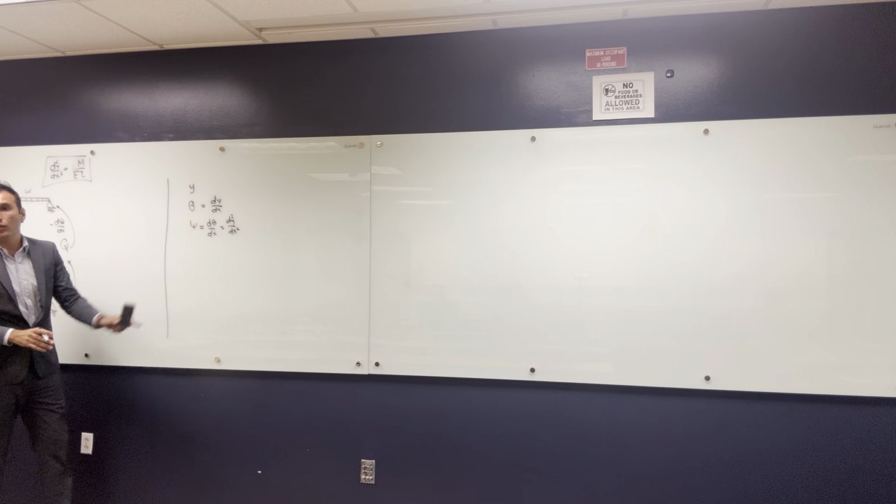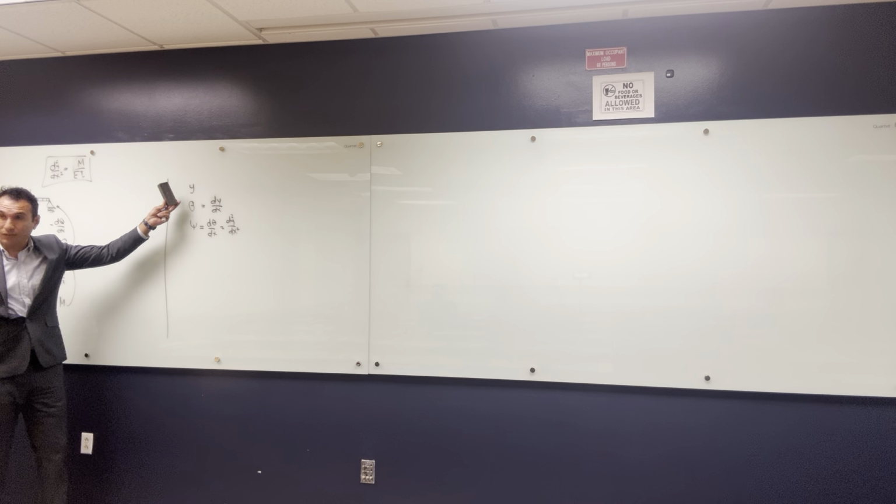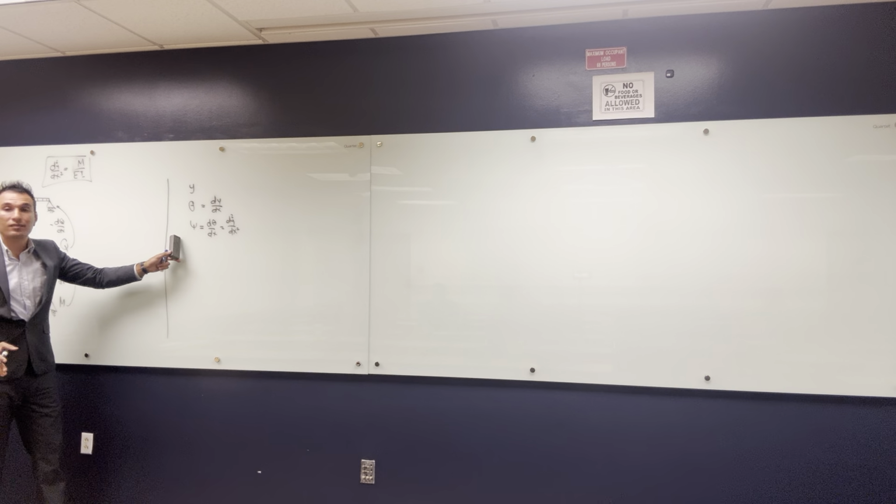So when we say deformation in a beam, we mean these three quantities, y, theta, and psi, because this is deformation, deflection, this is slope, and this is curvature, okay? So those are the three quantities that we are interested in, and somehow these quantities are related.